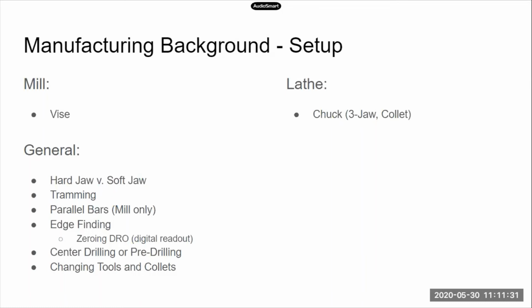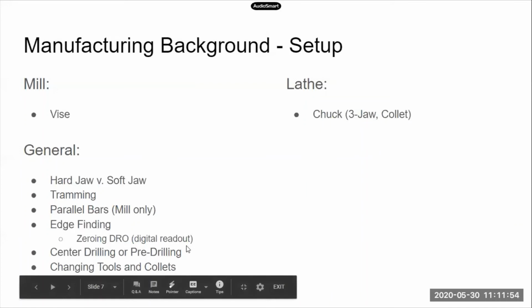Pre-drilling is much more applicable if you're doing screws in hardwood. Basically, it's creating a hole where you would want your screw to be. That way, some of the material is already removed, but not so much that the screw just falls in. Also keeps it in line.